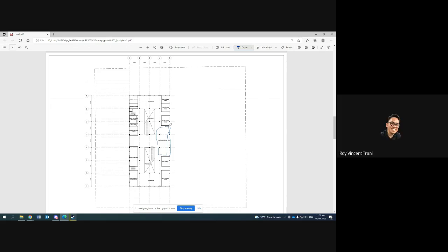So my suggestion would be to put all the staff spaces on the left side, so that it's one area for all the staff, and then all public spaces on the right side of this second floor plan. So similar to what we did with the hotel, you separate the back of the house and the front of the house. Okay, so you can just place a partition now, sir? Not even a partition, you just put all the rooms on one side. Okay, sure. Yes, sir.